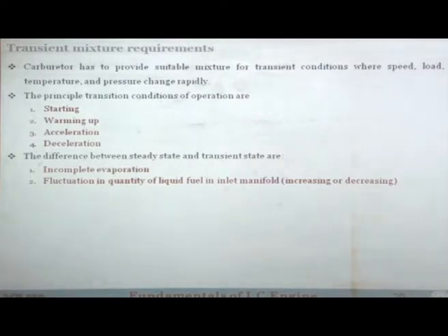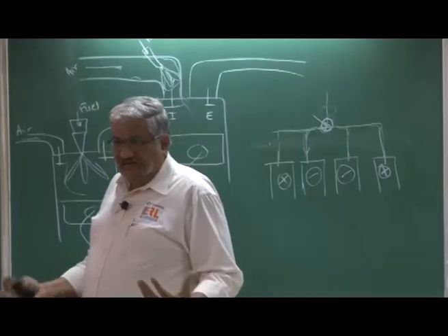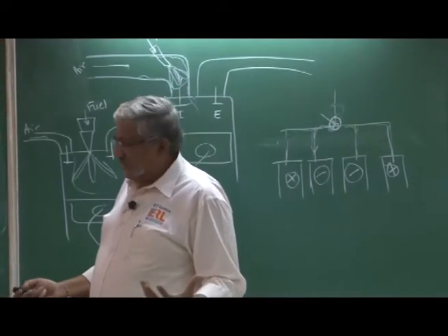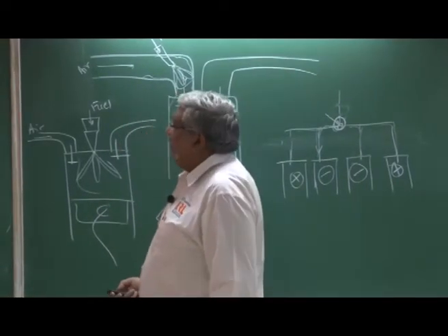So, where will it go? It will stick to the walls. So, there will be too much fuel in the intake manifold, it may increase or decrease depending on whether you are accelerating or decelerating, both are called transient states, okay. And then there will be distribution of the fuel among cylinders. I told you that more fuel is in liquid state, so you will have improper distribution of air fuel ratio between different cylinders of a multi-cylinder engine. So, this also happens, okay.